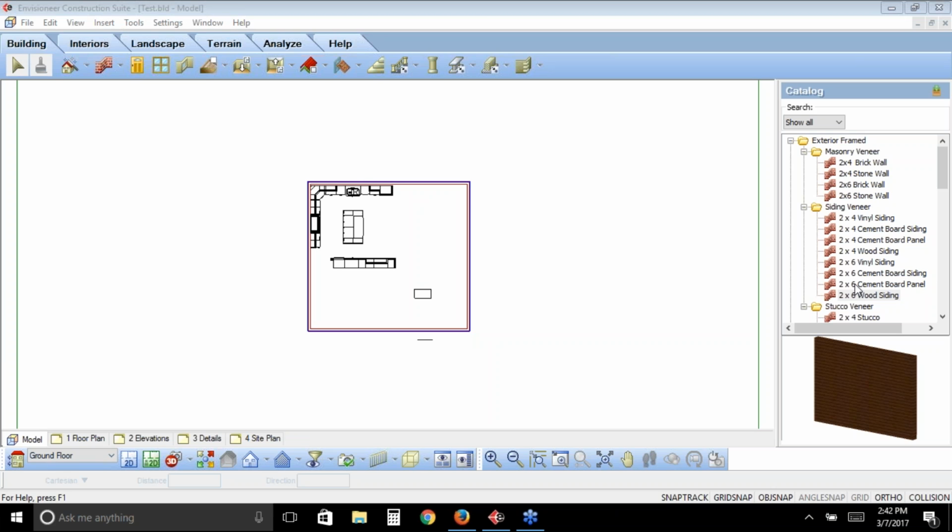If you delete a wall, how would you keep the window? You can't. If it's a window that you want to keep, it has to go out with a single wall. You could truncate the wall so that it's just a piece around that window, and then once you get it into SketchUp, it's easy just to take out those wall pieces instead of the whole model. So if it's something like a window or door that has to reside in and is a function of a wall, the wall has to go with them.